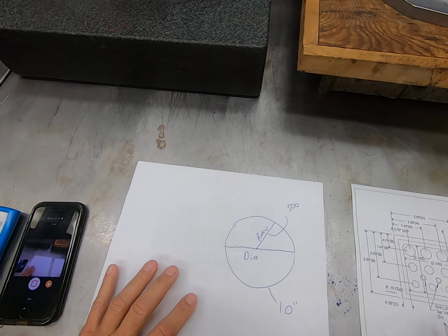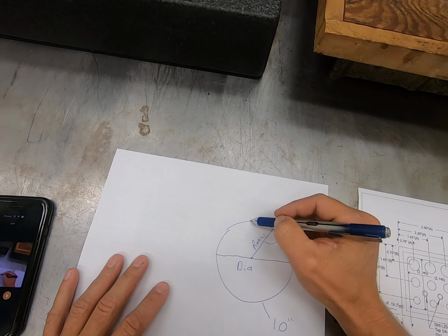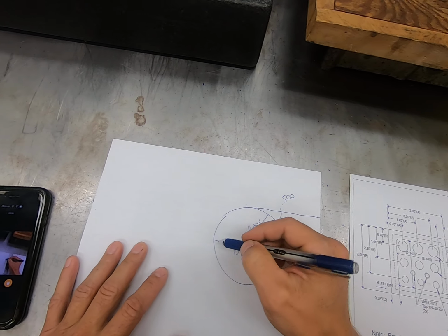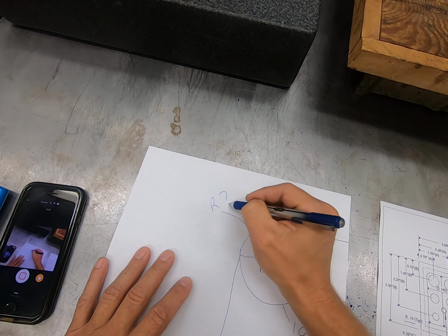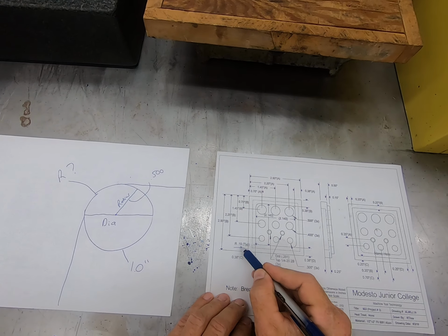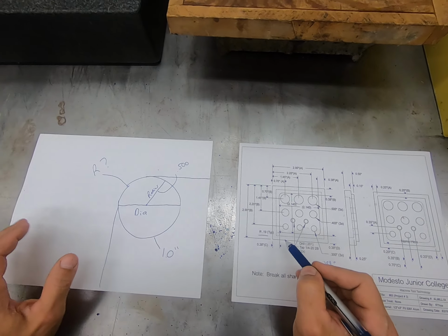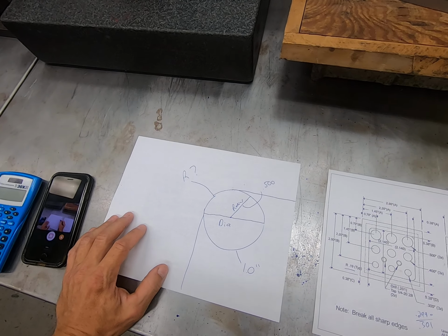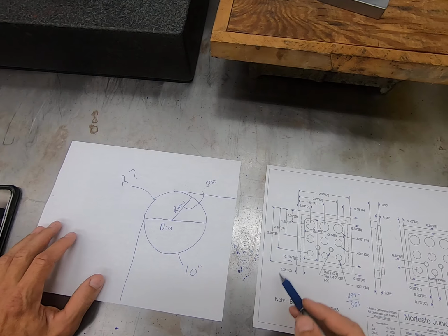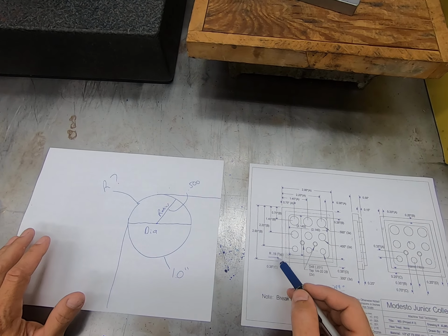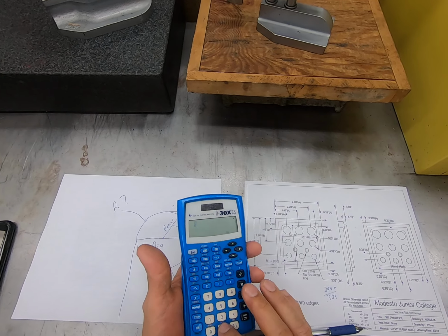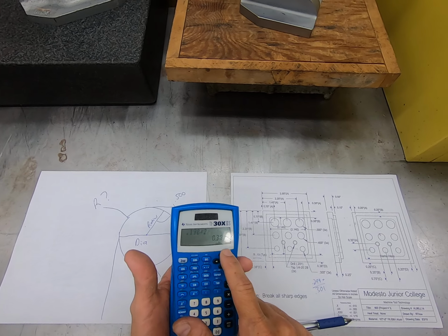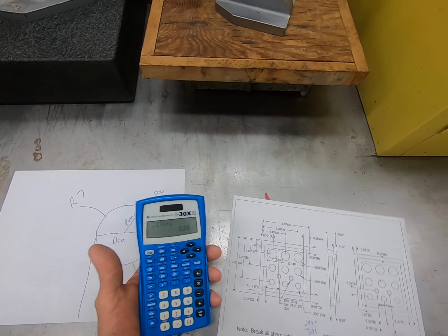So if you're gonna machine a corner in a part, what's happening is we have one edge here, and then one edge there, and we have a radius callout here. On our drawing, we can see the radius is called out at 190 thousandths. It's the same concept with the geometry. If it's a radius of 190, then I need a tool that is twice that size. So if I go to my calculator and go 0.190 times 2, I'm going to look for 380 thousandths. Well, let's go to our Starrett chart.